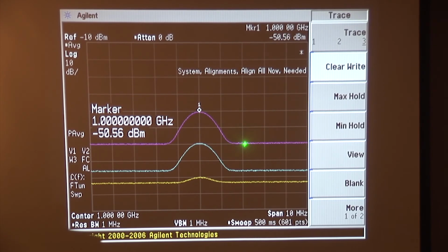So now we're hitting the point of diminishing returns, and this is where, as I said, people stick in an amplifier or even a set of amplifiers with even more gain. They buy themselves no more signal to noise ratio than they had to begin with, but the dynamic range just finally squeezes down to nothing.